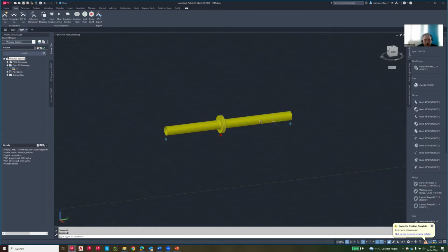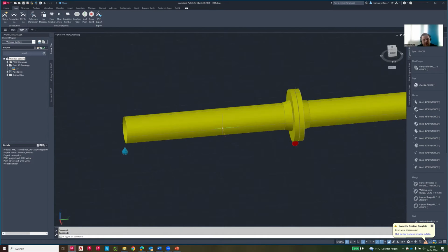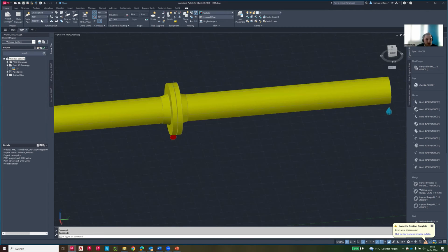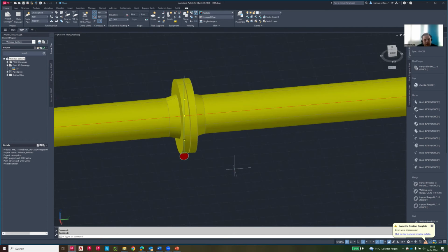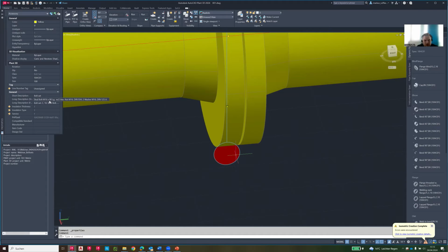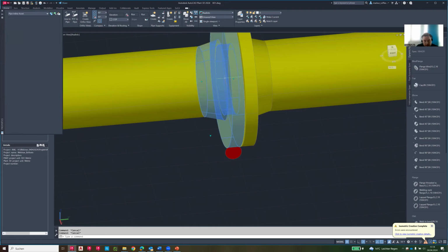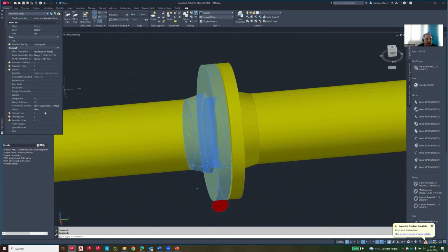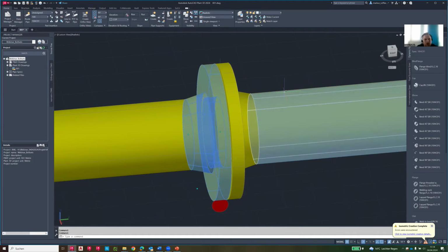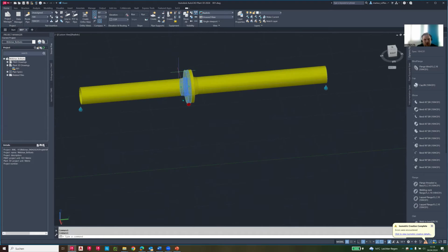What I did now is create a pipe with a simple welding neck flange connection. I used a standard pipe spec here, and as you can see, we have our bolt set there. Stud bolt is a standard bolt set in my pipe spec, so this is fine. The welding neck connections are created with the normal FL end types. This is an absolute standard flange connection. You can create it on your own machine, and it should look the same.